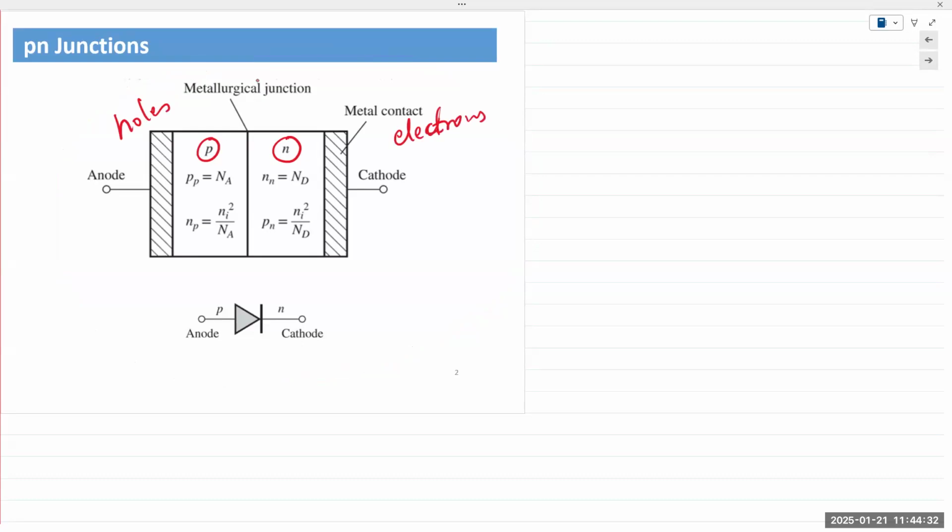When we are explaining this, typically instructors say, okay, we created a P-type material, we created an N-type material, and then we bring them together. But that's, again, for explanation purposes. As we just saw in this illustration, it's not as if we are creating two of them separately and then joining using some glue. That's not how it happens, right? So the moment we infuse an impurity in there, that's the moment when the junction is created. And that junction is illustrated here.